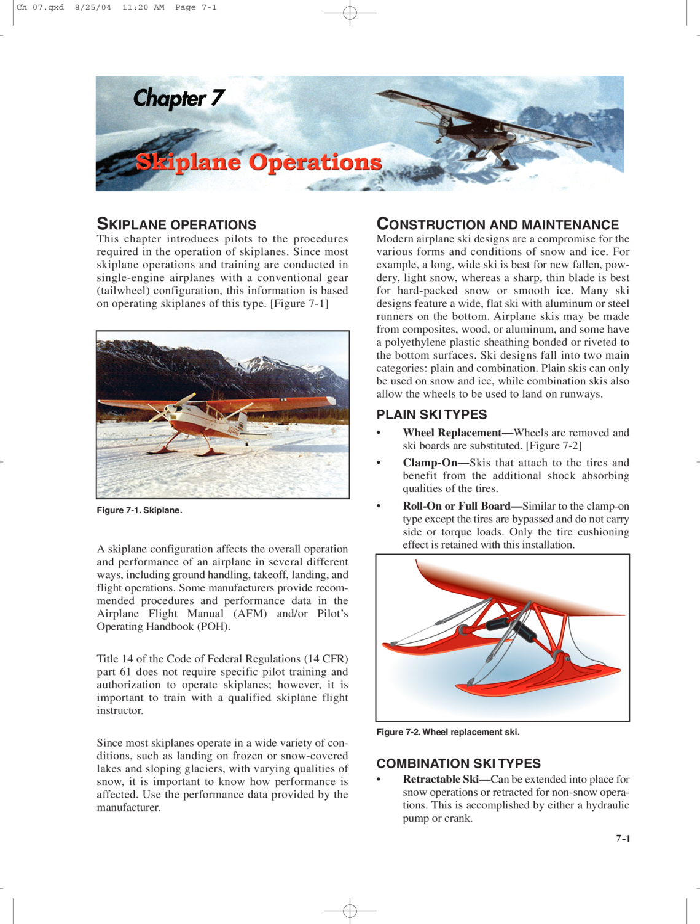Some manufacturers provide recommended procedures and performance data in the Airplane Flight Manual, AFM, and/or Pilot's Operating Handbook, POH. Title 14 of the Code of Federal Regulations, 14 CFR, Part 61 does not require specific pilot training and authorization to operate skiplanes. However, it is important to train with a qualified skiplane flight instructor. Since most skiplanes operate in a wide variety of conditions, such as landing on frozen or snow-covered lakes and sloping glaciers, with varying qualities of snow, it is important to know how performance is affected. Use the performance data provided by the manufacturer.